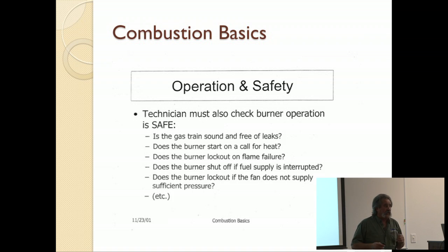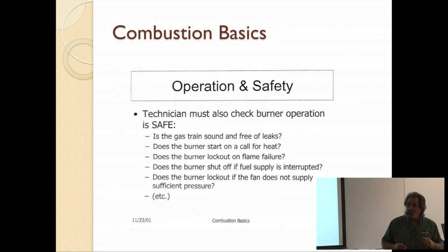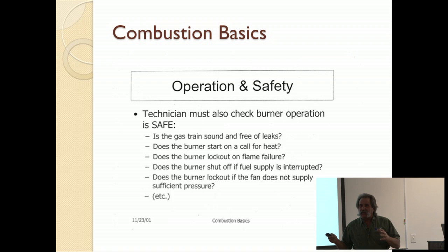Finally, one of the last steps that I almost always require is this: when you start this boiler, finally you think you've got it by the tail, you've got this thing in control, you're the master. The last thing you want to do is kiss it on the lips and walk out the door and turn the switch on as you do it. Stand away from the boiler when it fires the very next time. I can't stress this enough. This is a step that you absolutely cannot justify in your own mind.